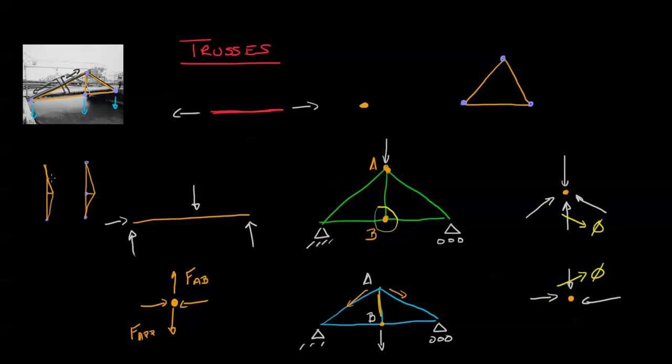At each of those pins, they run a stringer that goes all the way across. They run some sort of support. Maybe it's its own truss. Maybe it's some network. Maybe it's a beam, whatever it is. And it's supposed to carry the weight of everything that's on top of here. There's not a whole bunch of small ones that carry the load; rather there are these three big ones that carry the bulk of the load. They put it on the pin, and then to make sure they cover everything, they'll connect these with members that go like this.